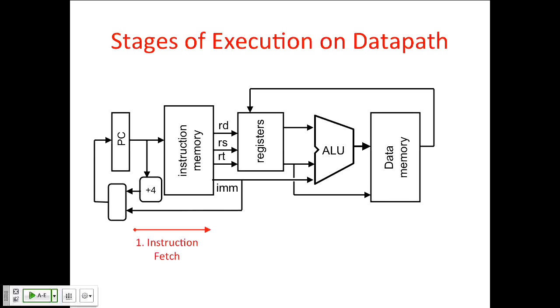And that's the end of the instruction fetch phase, right? You've taken the program counter, you've read the memory, and produced the bits that are at that memory location. The other thing you do on the side is you increment the program counter by 4 and get this ready to be written to the PC for the next instruction fetch. Notice there's a mux here because sometimes you don't always go sequentially adding 4. Sometimes you do a branch or a jump. So you need to worry about putting in a different value other than PC plus 4 into the PC. Okay?